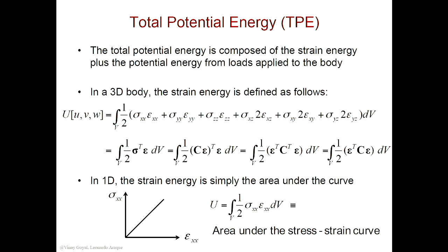So if I look at a 3D body, basically the total potential energy of a system, of a body, is essentially the strain energy stored in the body plus the work done by the external forces. That is the total potential energy.